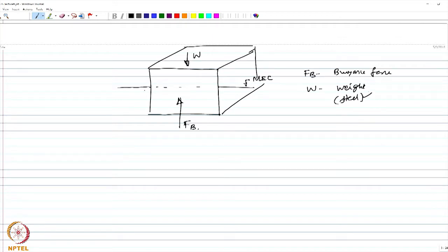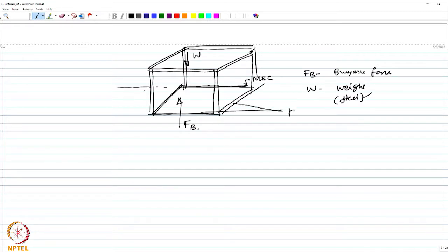We all agree that TLPs are constructed of steel. Therefore, we know the density and the volume of material of column members, like I am drawing just now, and the pontoon members which are horizontal, which I am drawing now at the bottom. They are integrally connected and welded together. However, the structure is transparent and hollow in between, so waves can pass through the structural system. The horizontal members are referred to as pontoons and the vertical members are referred to as columns. All are hollow steel tubes of diameter about 12 to 16 meters. As the wave passes through, the transparency of the system enables flexibility and recentering capability for the platform.